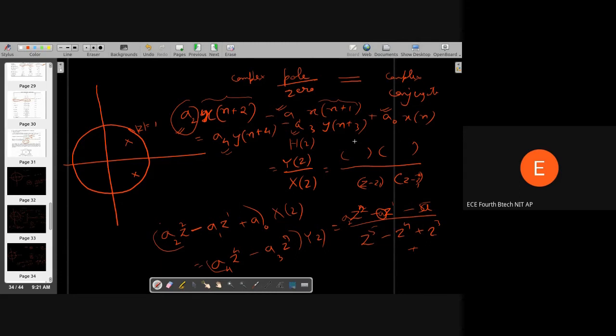Complex numbers have their purpose, but obviously in the time domain, why would we multiply with a complex number? We will not achieve anything by that. Because our coefficients in the time domain difference equation are real, in the Z transform, if we have a complex pole, it should also have a complex conjugate pole. Similarly, a complex zero has a complex conjugate zero. They come in pairs.